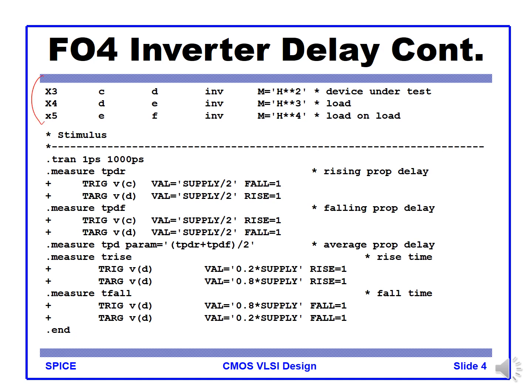Continuing here, 3, 4, 5 different inverters are defined with a larger multiplication factor there. We have a transient definition here. We have a measure here. So actually our delay measurement is done on the X3 block.